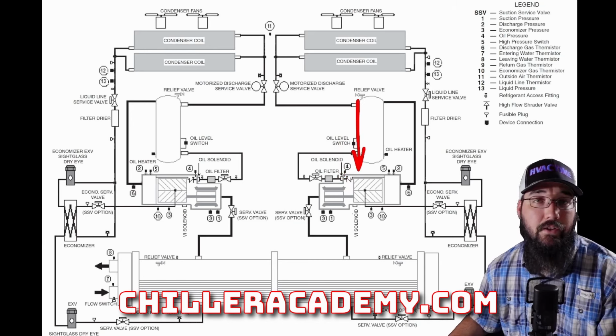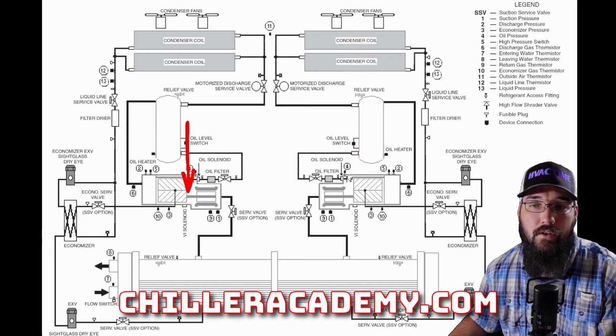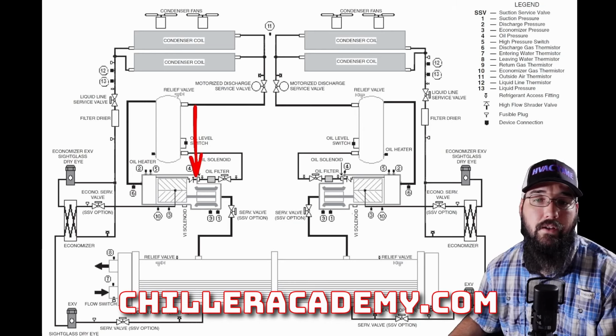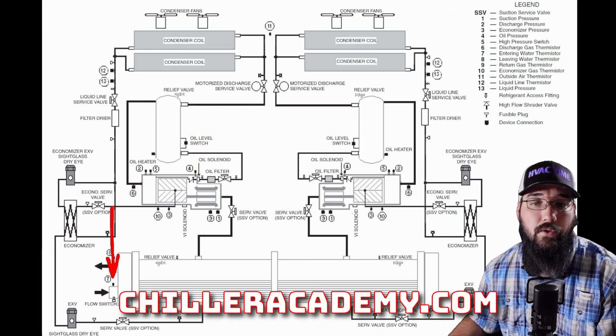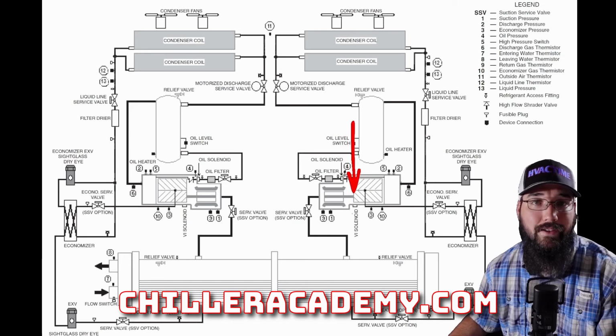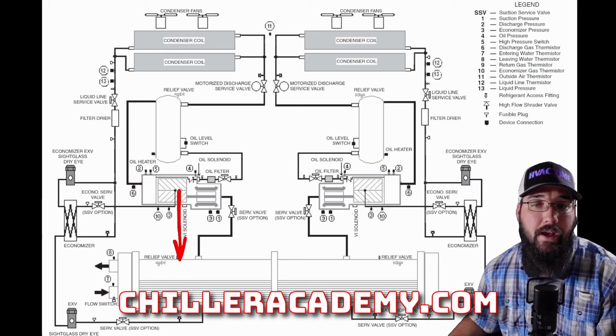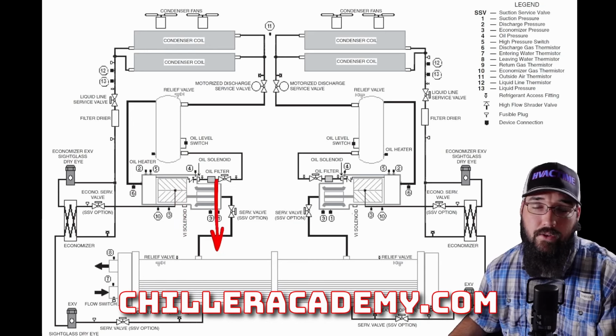Once it gets to maximum, it's going to stay there and it's not going to back down. Then it's going to bring on compressor 1 as lag. It's going to ramp up until it gets to whatever it needs to hit set point. And then as the load falls on the system, it will slowly back down circuit 1 as the lag, but it will not touch circuit 2. Circuit 2 as the lead will stay at full speed, and then circuit 1 until it's able to back down and completely pull out of the circuit.